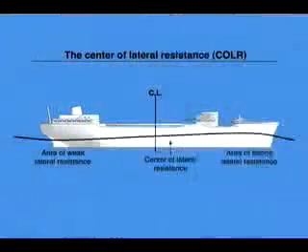The field of pressure, bow wave, and the stern sub pressure under headway shifts the center of lateral resistance towards the area of higher pressure. This is mainly due to the positive pressure built around the bow in the forward motion, which creates a more resistant surface for the hull to lean on when pushed sideways.